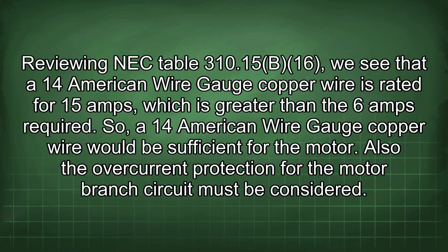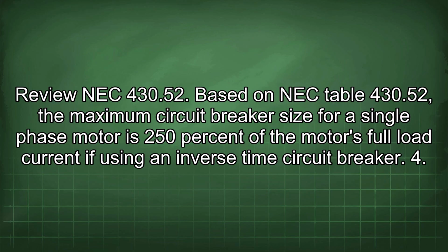Also, the overcurrent protection for the motor branch circuit must be considered. Review NEC 430.52.